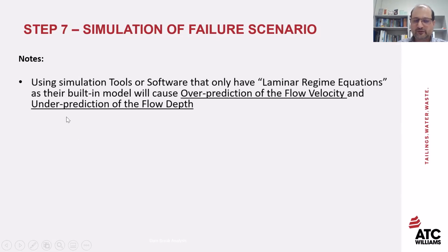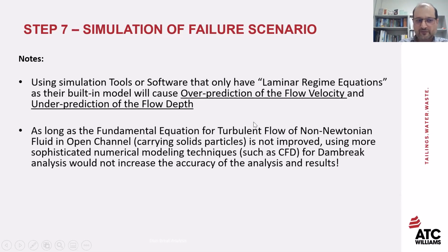Also, we have to keep in mind that using simulation tools or software that only have laminar regime equations as the built-in model will cause over-prediction of flow velocity and under-prediction of the flow depth. One other thing to remember is, as long as the fundamental equation for turbulent flow of non-Newtonian fluid in open channels containing solids is not improved, using more sophisticated numerical modeling techniques such as CFD for dam break analysis or similar sort of problem would not increase the accuracy of the analysis and the result.